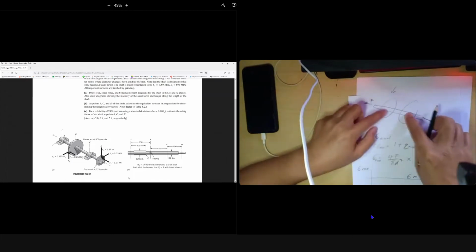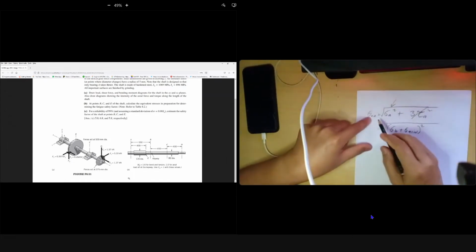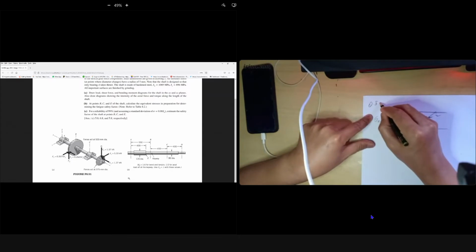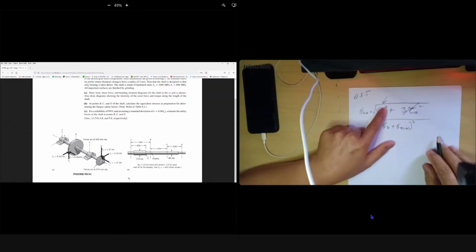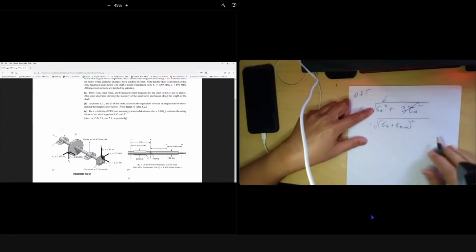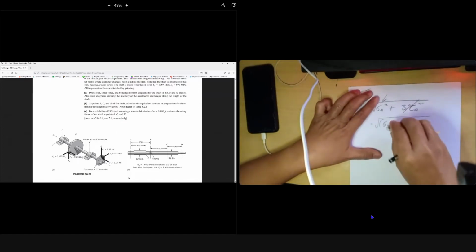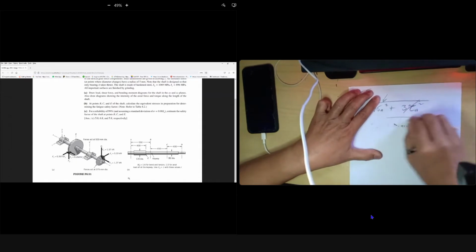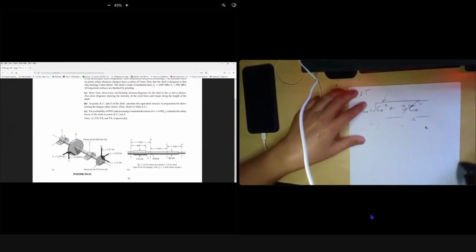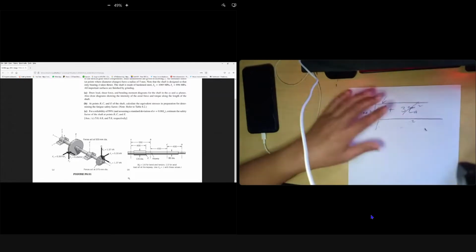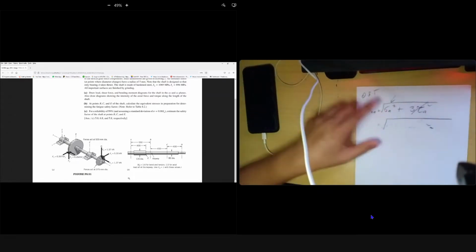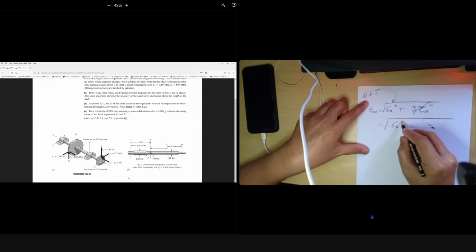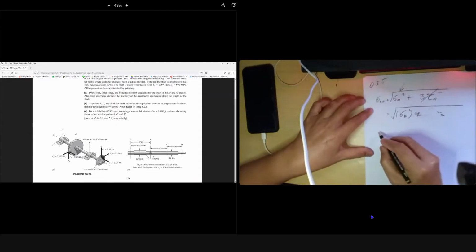If we have a case with a pulley and we pass additional load, our equivalent stress sigma EA based on DET is, remember the equation, sigma alternate squared plus 3 tau alternate squared. Sorry guys, my mistake. What do we have for sigma alternate? Sigma bending, right? So sigma bending squared plus the torsion term. Sorry guys, my mistake.